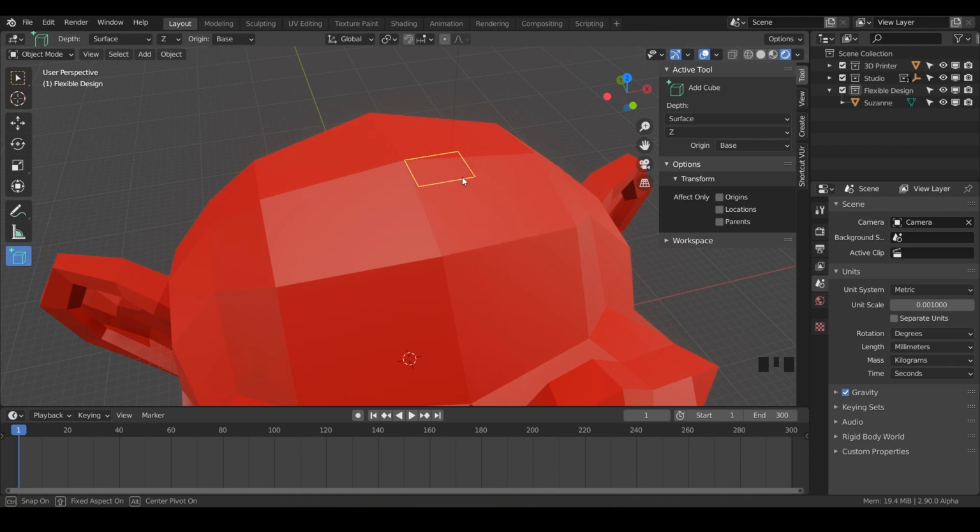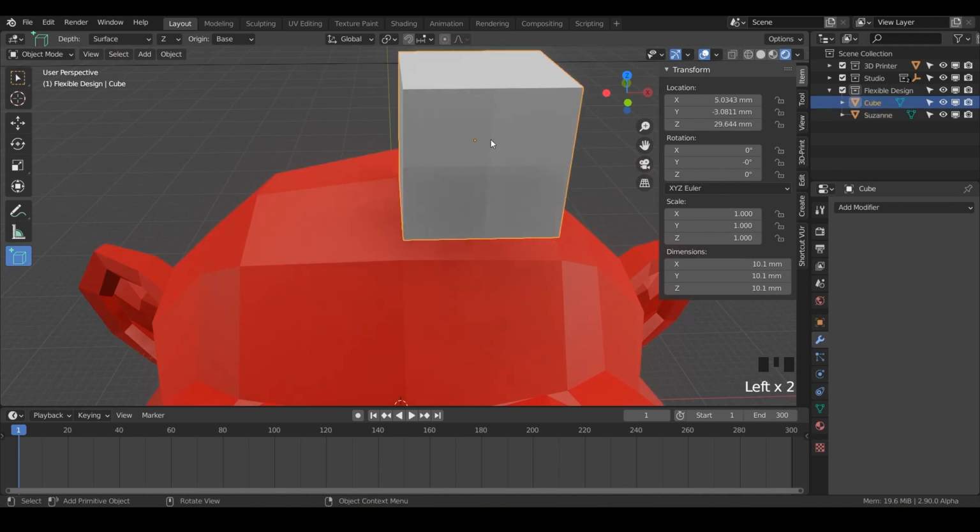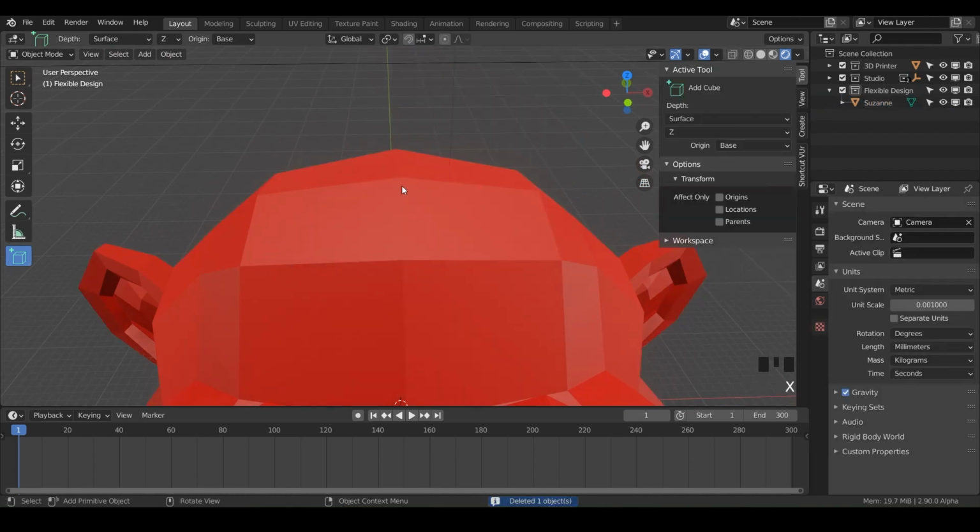So that's pretty cool. You can also hold Shift, and that will lock it in so it's exactly even on each side. And I could go up or go down, but if I hold Shift while doing that, it's just going to lock it in so that it's a perfect cube in every direction. So again, just to clarify and kind of drive this home, click and Alt will go from every direction. Just clicking will do base, growing from the corner.